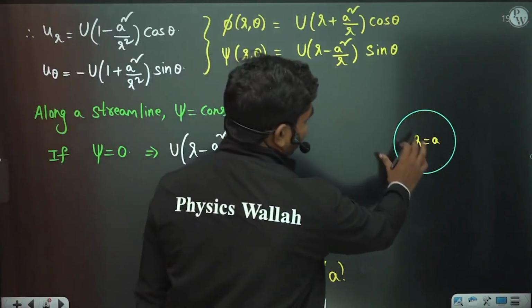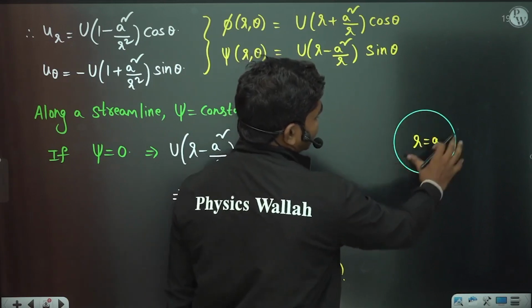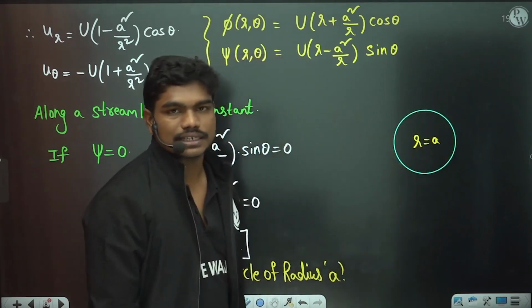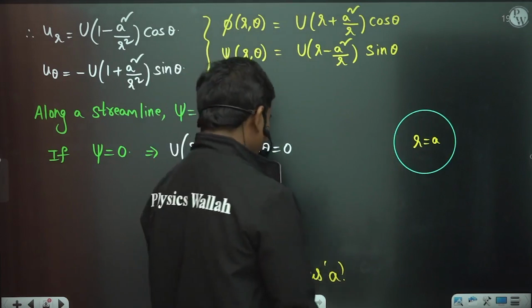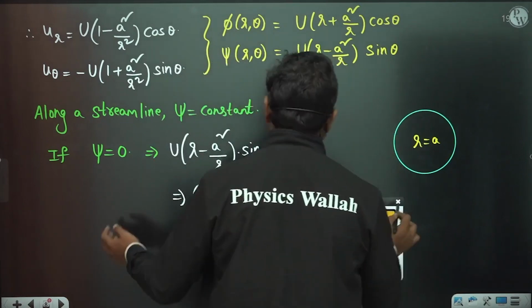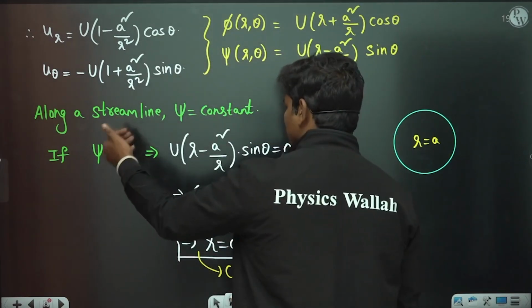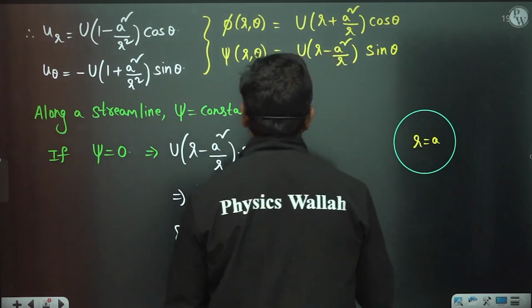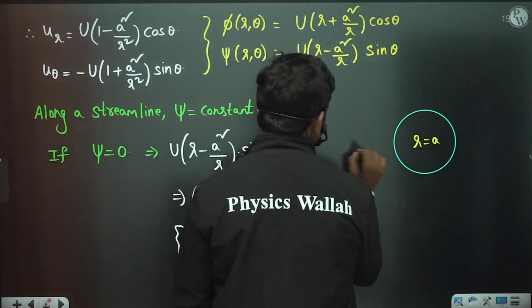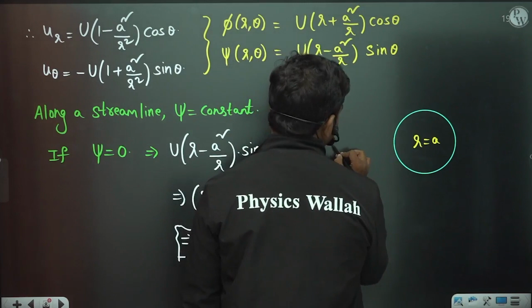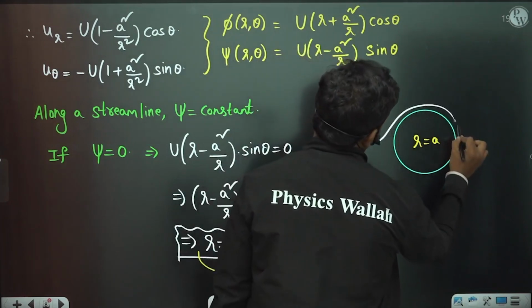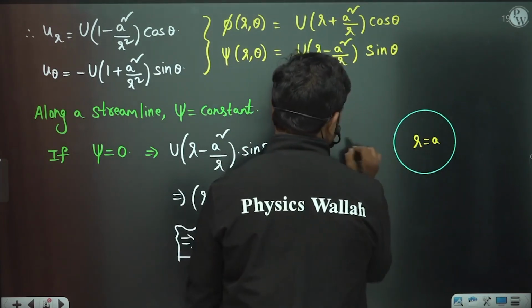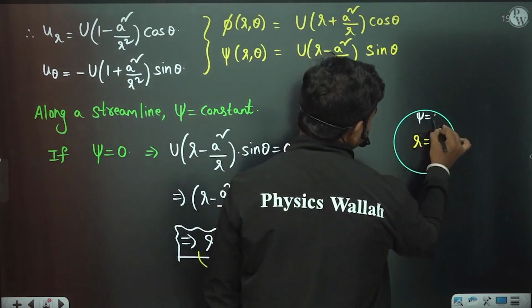Okay, so whenever the velocity of the particles here is 0, then definitely this cylinder is a fixed cylinder actually. Now if you take the flow on this, if you plot different streamlines again for psi equal to 1, 2, 3, all these things, then the curve that we get in this case is something like this. So this is psi equal to 0.